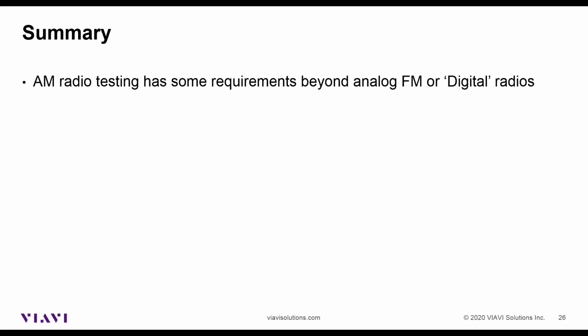So in summary, AM radio testing has some requirements beyond analog FM and digital. Again, think about the quality of the AM depth measurement, and if that's really important to you, in which case you've got to think about using the correct IF filters and reducing the noise that's added by the test set, which includes phase noise plus other broadband noise. That's broadly equivalent to the white paper we did for the digital radio tuning.